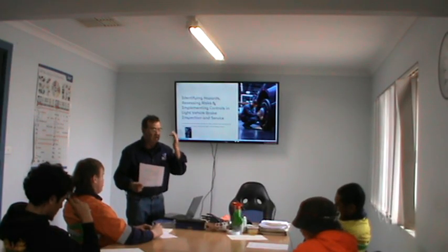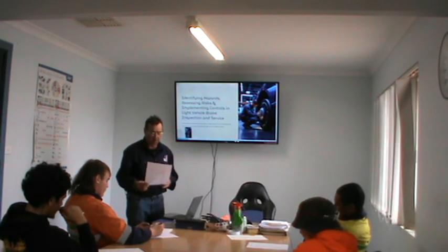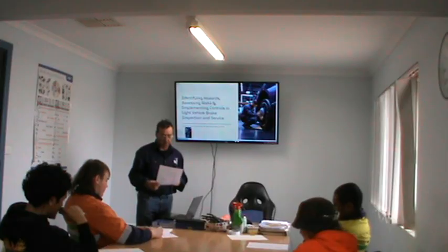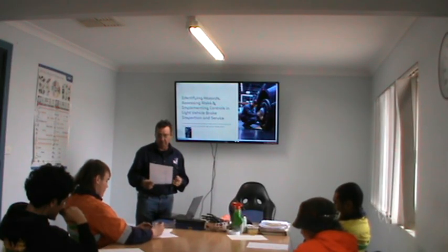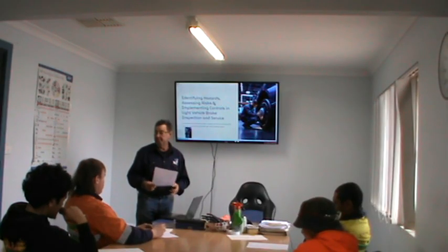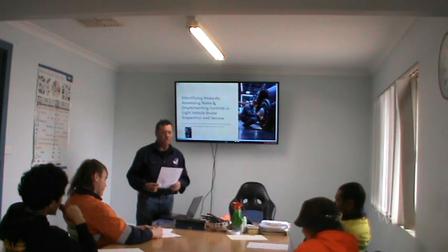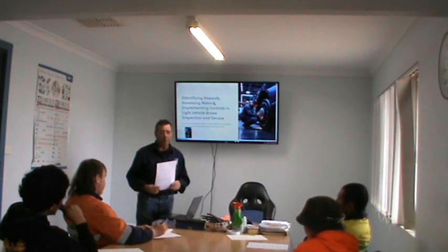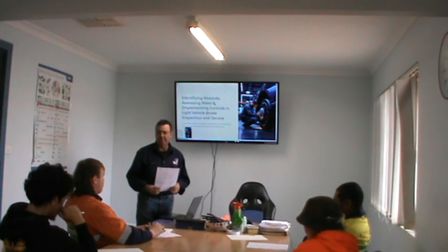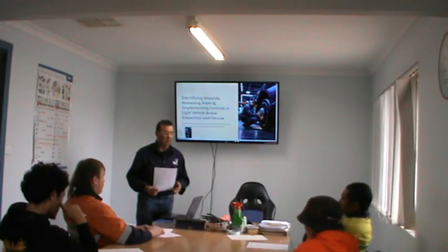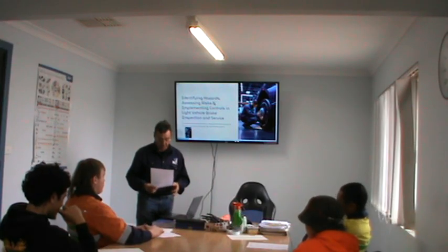No, we've got to be able to see what we're doing. True or false: lifting heavy brake rotors without assistance or equipment could lead to a manual handling injury? True. Could do, couldn't it? Most brake rotors in light vehicles aren't that heavy, but they can be. If you're dealing with trucks, then most definitely extremely heavy.